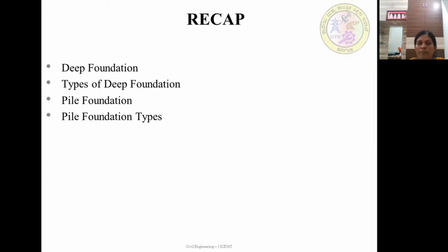Load is heavy and non-uniform. In such situation, it is necessary to provide pile foundations. Raft foundations are costly and adoption is impossible due to local difficulties. In such situation, pile foundation is preferred. During heavy inflow or capillary water, where it is not possible to maintain foundation trenches because of presence of water, and it is not possible to timber the excavated trench.